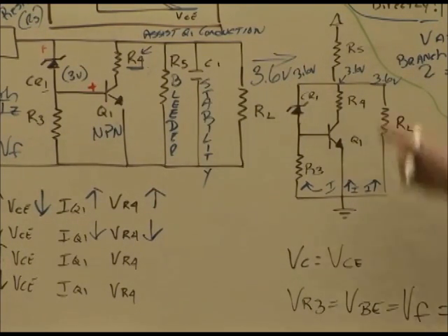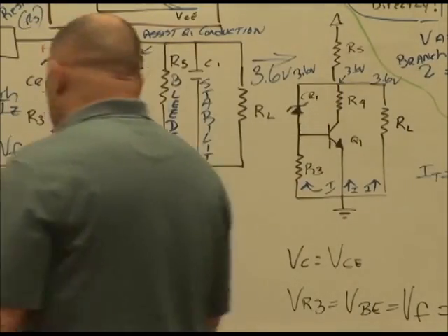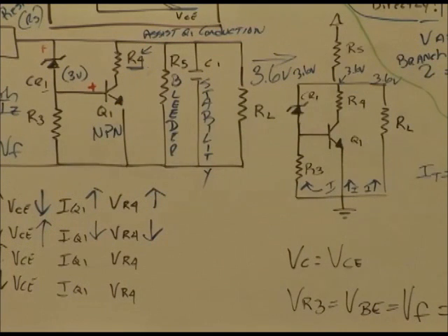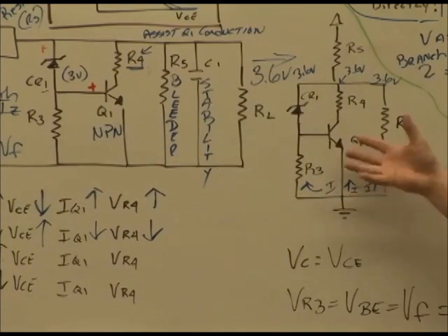See what's going on here? What's additive in series? Voltage. Voltage is additive in series. So how many elements are in this series branch? We've got R4. What else is in that branch? Q1. How many components are in that branch? 2. If VR4 goes down, and I'm trying to equal 3.6, what does the VCE have to do to equal? Increase. Everybody understand that? Yes, sir. That's what's called Kirchhoff's voltage law in a series circuit. See how simple I'm trying to make it for you?